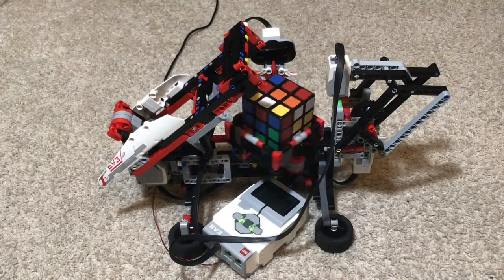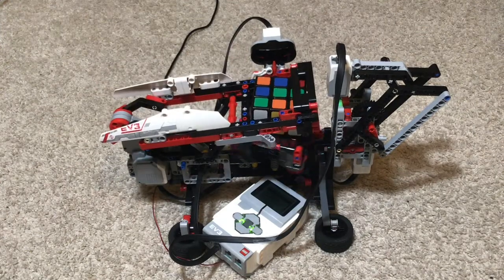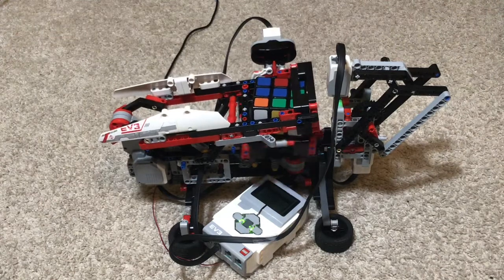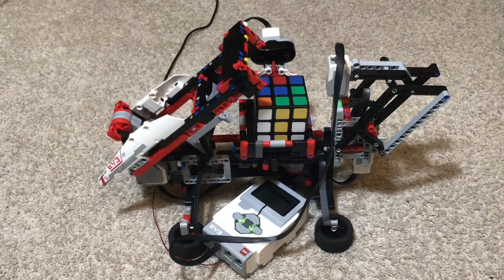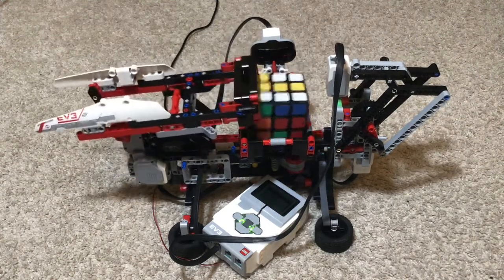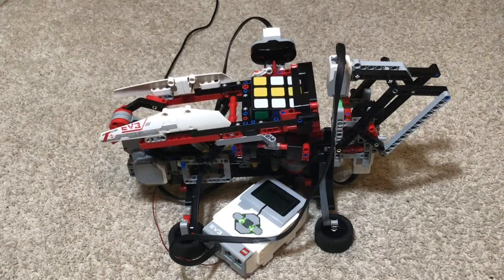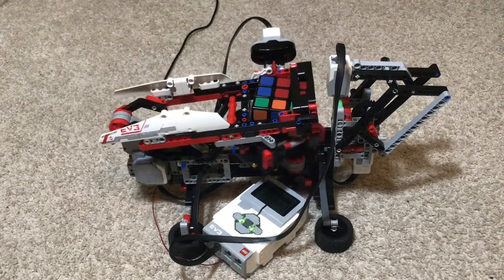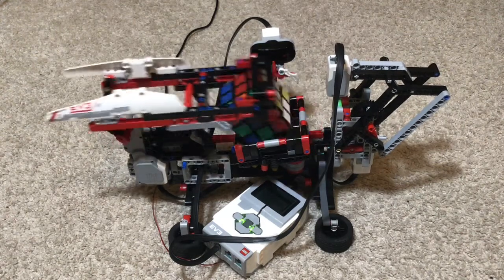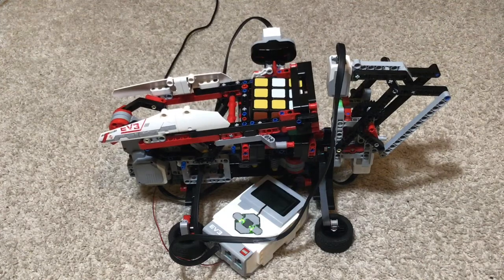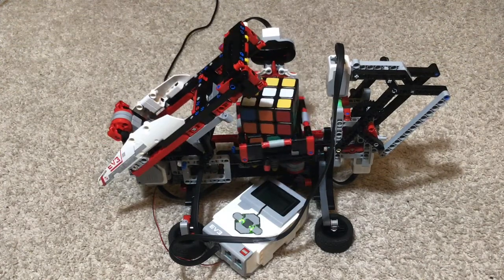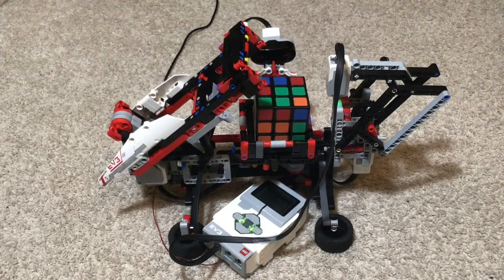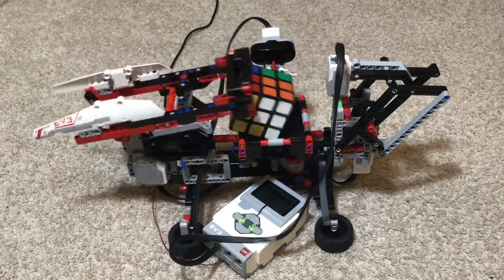I've also had many problems, modifications, and failures during the process. One of the earliest ones, even before I started the Mindcuber adventure, was that the battery would run out on the EV3 brick very quickly. It would be 6 batteries at a time, and it was using a lot of our batteries. So I made this wire that hooked up to the battery port and then connected it to a plug, so we could just plug it in every time that we wanted to use it. The only time that this wouldn't work was if the robot was moving around, but the Mindcuber was a stationary robot, so it doesn't matter as much.